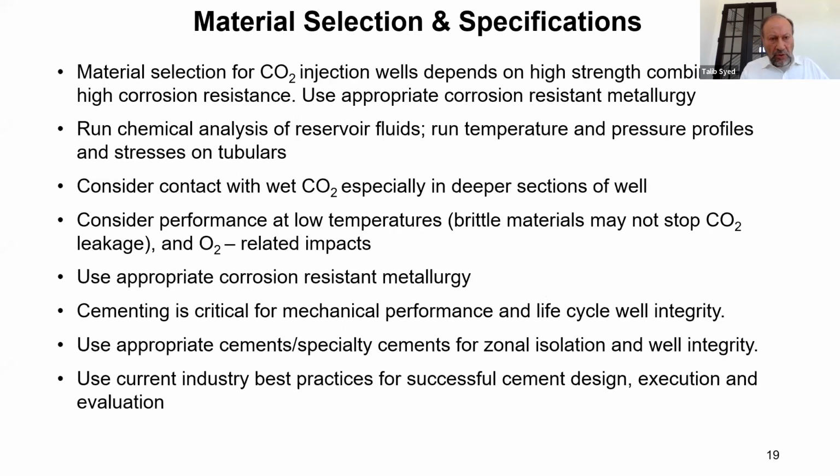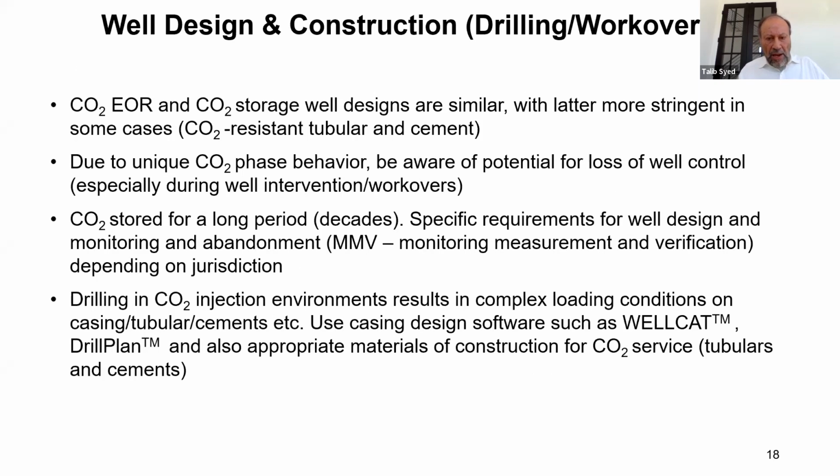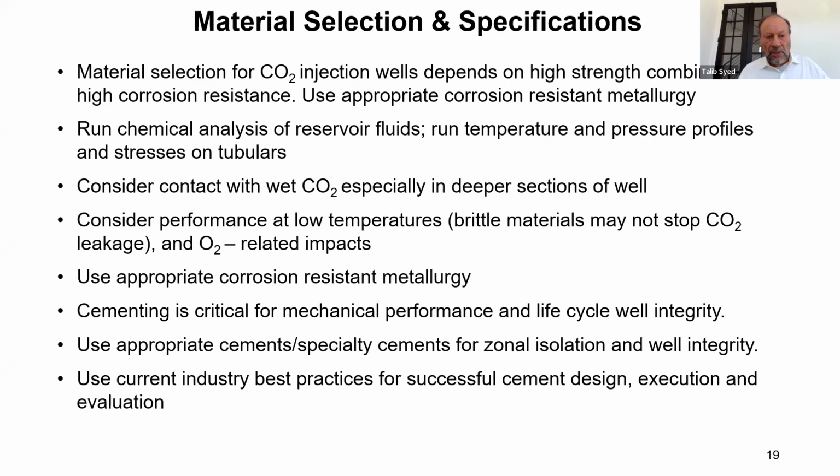For CO2 storage, you're looking at many decades of time frames, and complex loading conditions. We mentioned that earlier with WellCat, the drill plan, appropriate software. Metallurgy is very important for the corrosion resistant characteristics against CO2. Remember, we are looking at long-term storage.